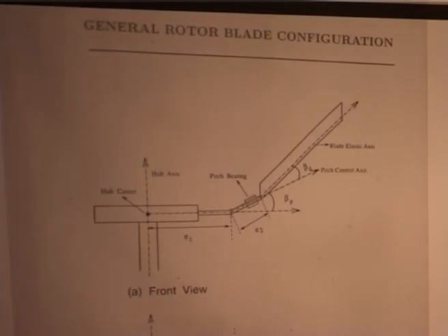In that problem, pre-droop gives some damping, but it will increase the vibratory load, okay, in lead lag. But pre-cone will not give the damping, but it will reduce the load. So, you have to see the trade off, what you want, okay, whether you want higher load, vibratory load, not mean load,